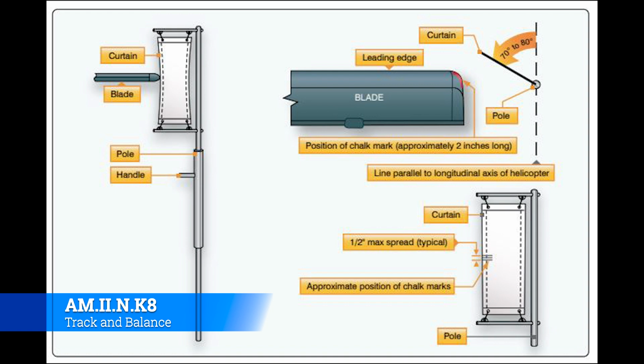The blade tips are marked with chalk or a grease pencil, and each blade tip should be marked with a different color. All the blades are typically like the red blade, the blue blade, the green blade, or whatever, depending on how many blades you have. So as they come around, the chalk method, or the little flagpole, you stick it to the rotor blades. The chalk method will slap the white curtain that's there and make a mark, and then you'll know that the red blade's high, the blue blade's high, whatever, one's low.